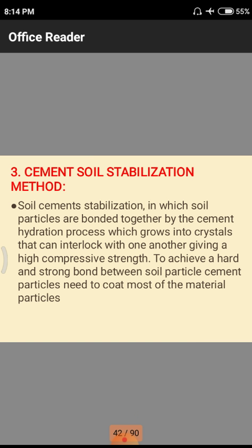Normally lime is a product which has a chemical content of calcium oxide and a few percent of magnesium oxide as an impurity, so that those two combine with the help of water or any other mechanical parameter and mix with the soil and give a huge amount of strength compared to the previous soil.